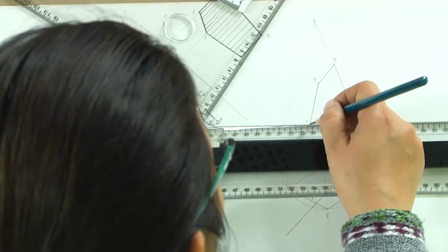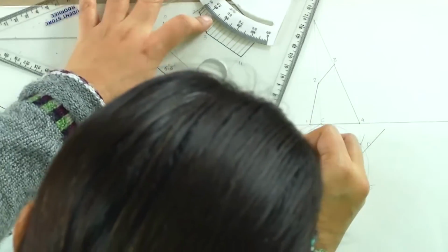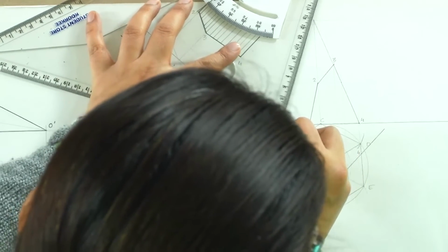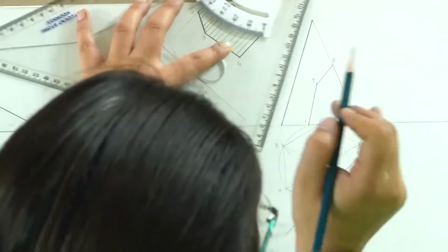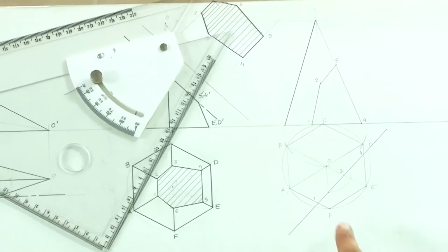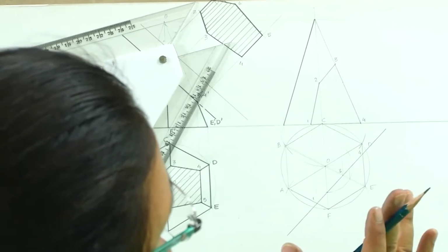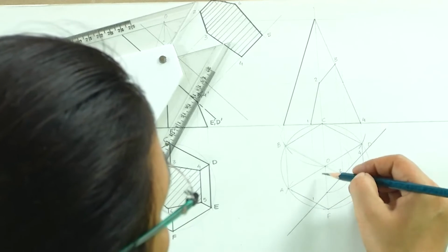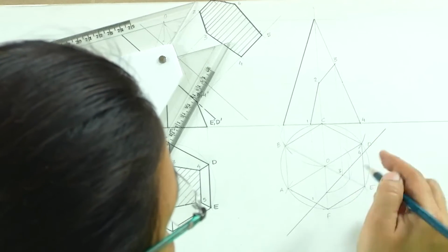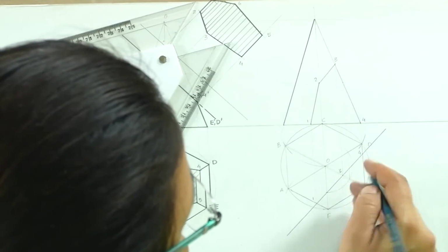Two and 3, the side, the edge OA, it remains intact. So, it will be seen as it is. If you see clearly which all surfaces are getting cut, AOF is cut, OFE is cut, number 2, OED is cut, that is third, and in the base we have this cut.